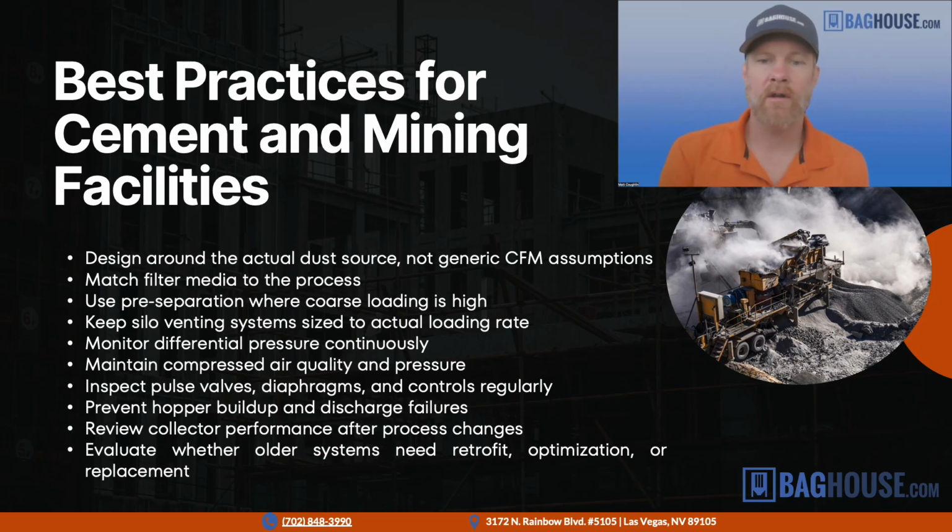Another thing to keep in mind here is that process changes are often unavoidable, but when your process does change and you move the equipment around or you add something, you take something away, that may invalidate the original design basis for your dust collection system. So, if you have an older system and it's not performing as it should, it's likely that some things have changed over time. The system balance is different.